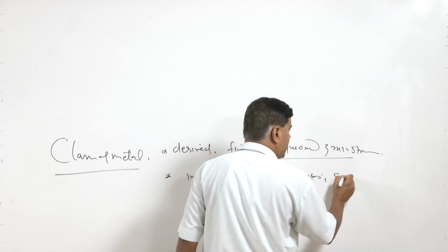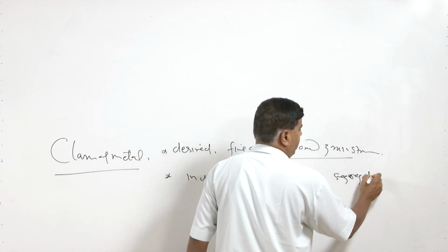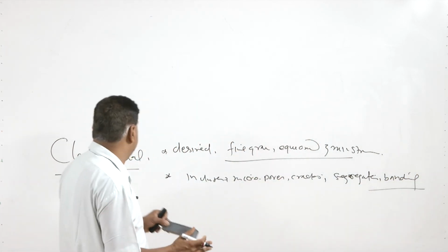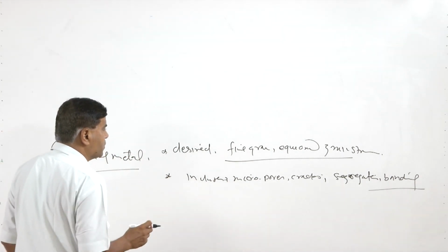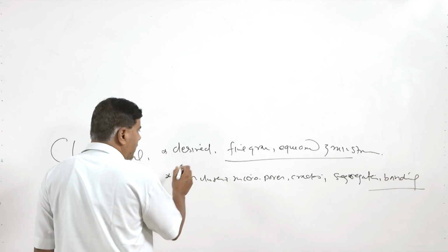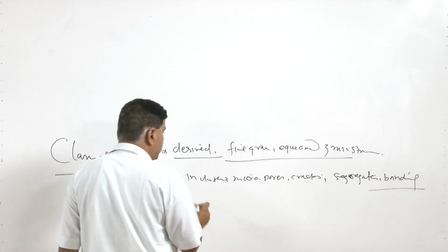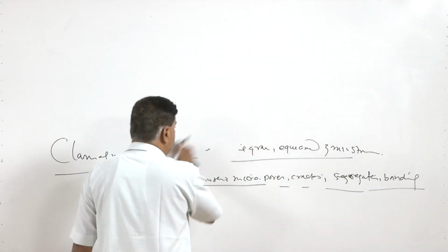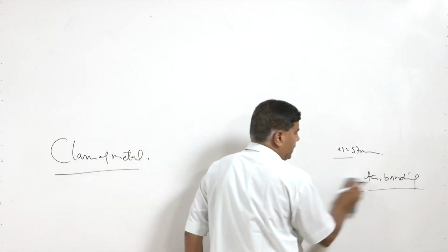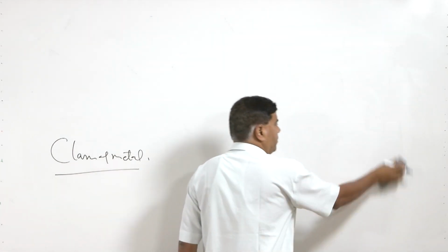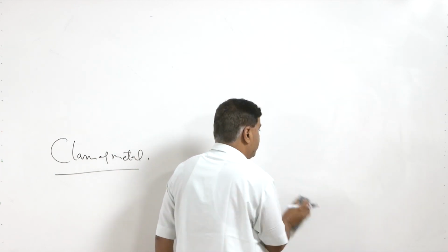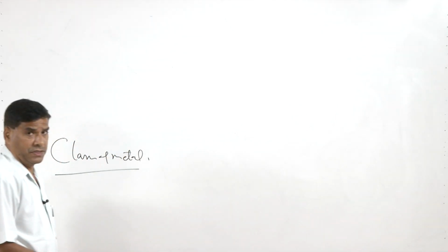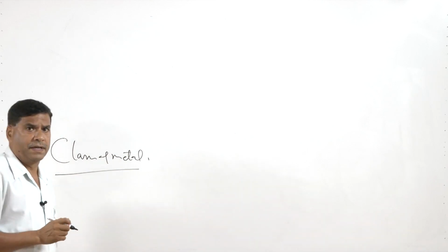There can be segregation or there can be banding. So, these are the metallurgical defects which can be identified through microscopy or metallography only. So, whether the desired features are there or whether undesirable features are also present, that will help to identify the class of the metal, whether it is of premium quality, free from impurities, defects, undesirable gases, and the kind of grain structure and grain shape it has.